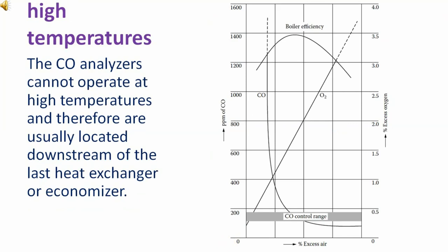The carbon monoxide analyzers cannot operate at high temperatures and therefore are usually located downstream of the last heat exchanger or economizer.